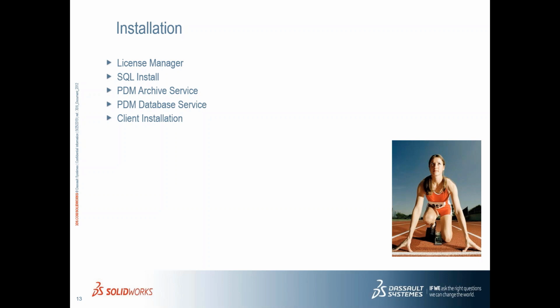So first, step number 1 in the installation is we have to install the license manager. Step number 2 is PDM is built on what we call a database. The database that we use is actually called Microsoft SQL. It is a very familiar, very popular database tool, and that tool has to be installed on a server that all your clients will be connecting to. We'll come back to what the database does in a second.